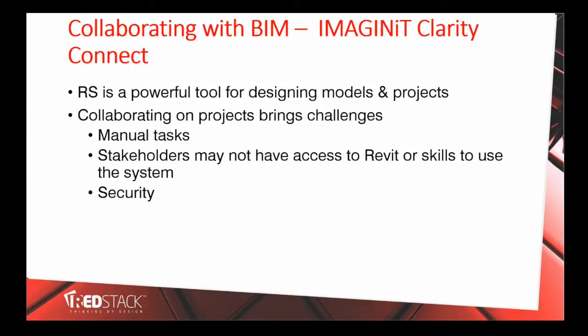There's also an area of concern, which is security. With Revit Server, whilst it is possible to share data with different stakeholders, the security model allows all participants to see all folders and all projects, which may or may not be desired.